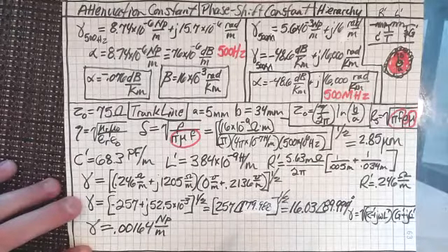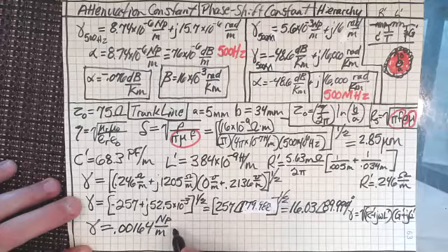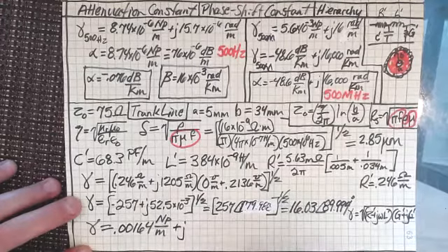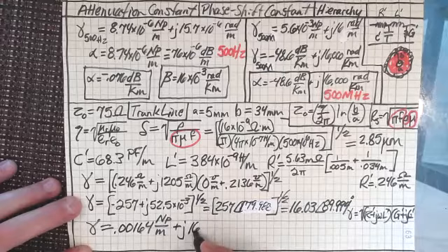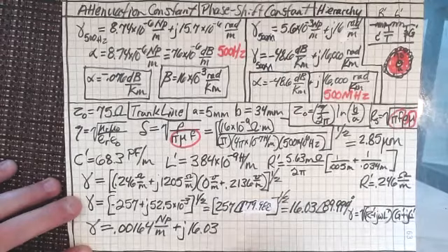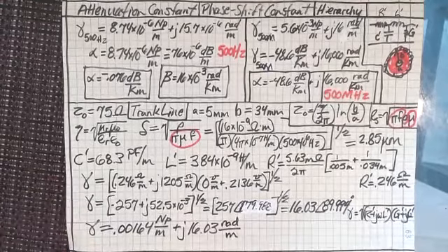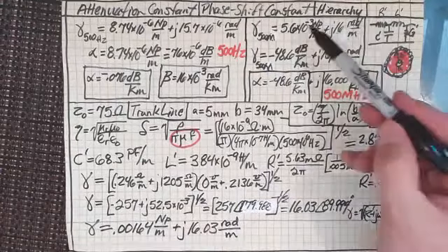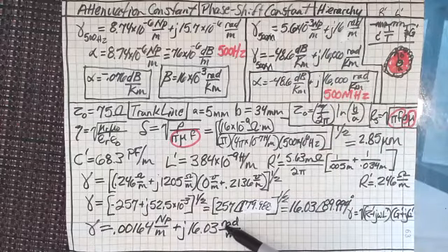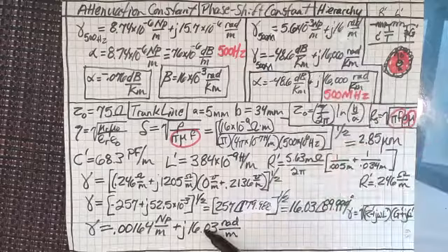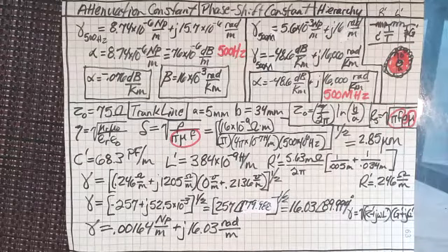That's my attenuation coefficient, plus J is just a marker, 16.03, and I don't want to take that out any further, radians per meter. So if you look at it, the 16 radians per meter here and the 16 radians per meter here, irrespective of the size change, is the same, isn't it? All right. Just so that you can see that.